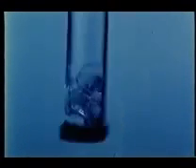The noise is a result of shock waves generated upon bubble collapse. The pressures associated with collapse are high enough to cause failure of metals. Here is cavitation damage on the runner of a large hydraulic turbine which operated under cavitating conditions for an extended period of time.